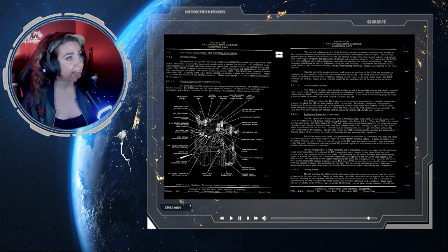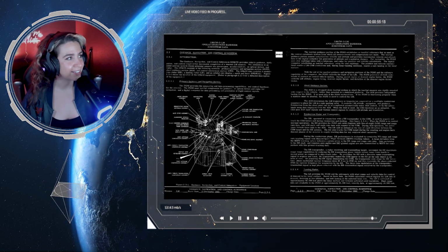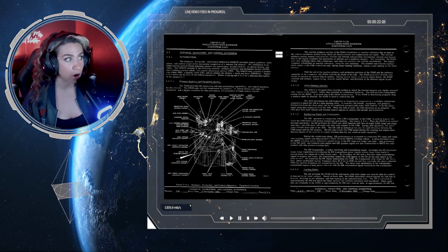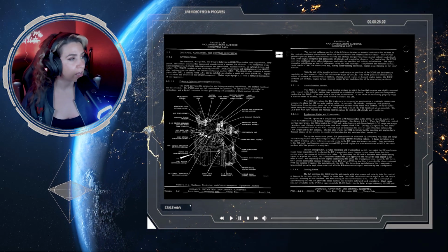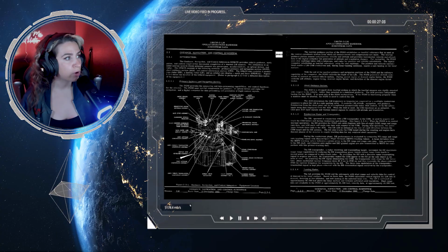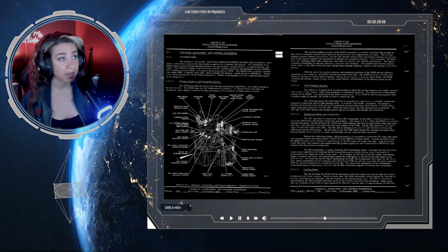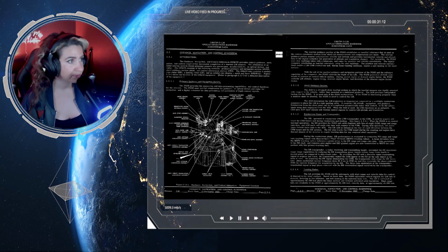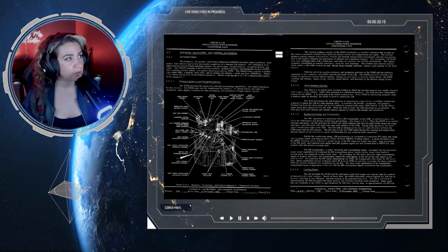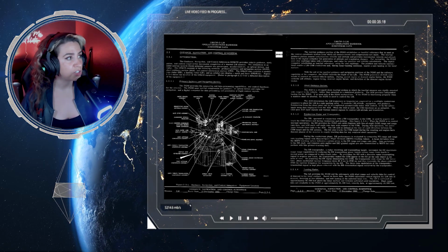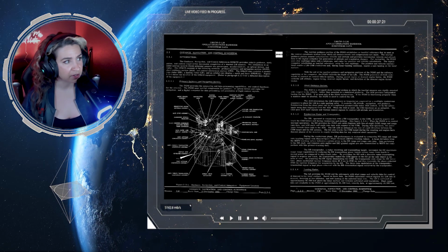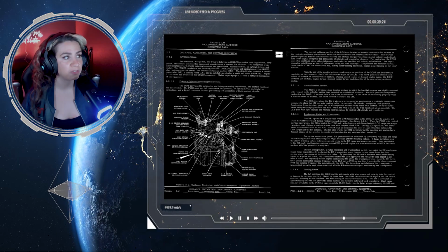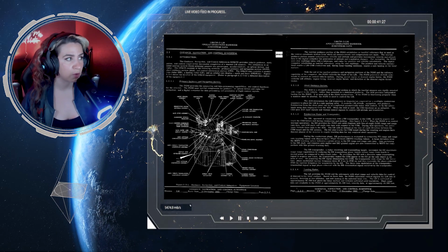The GN and CS also contains a rendezvous radar, or the RR, a landing radar, LR, and an orbital rate display, Earth and Lunar, or DEAL. Figure 2.2-1 shows the location of the GN and CS equipment. Refer to paragraph 2.2.4 for a detailed description of the equipment.